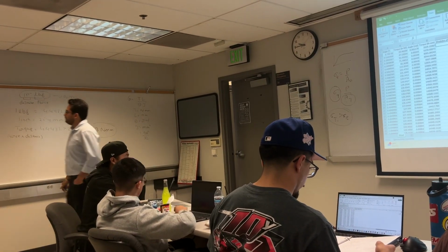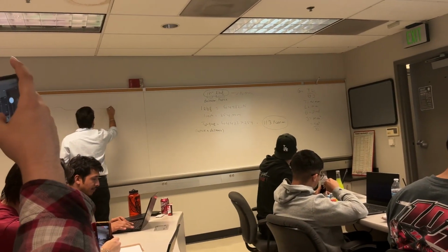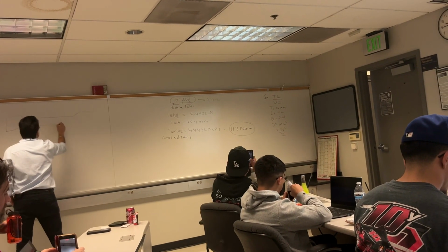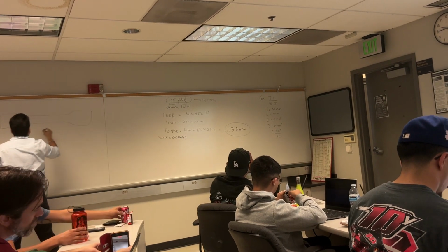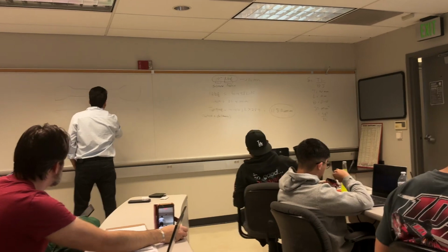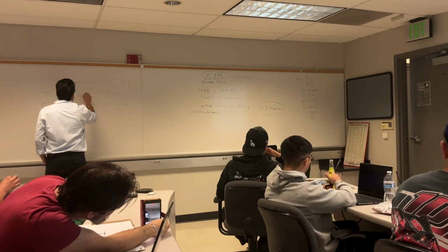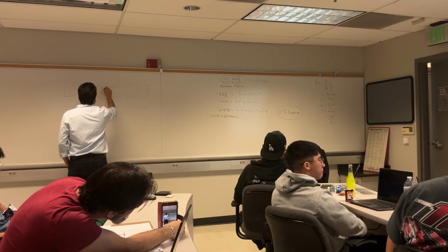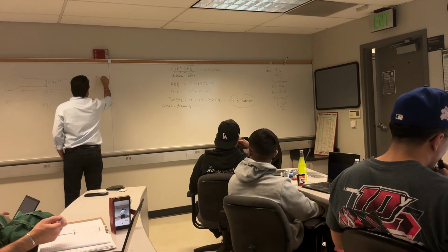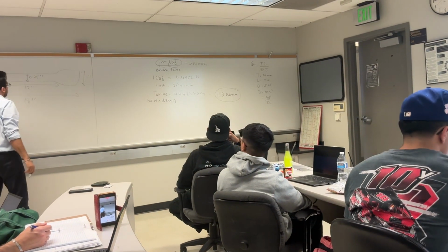What was the standard? This is the sample, right? Like that. So this total length was 18 inch. Gauge length was 12 inch. This was 0.75 inch. This is 1 inch. Right? That's it, this is what you need.